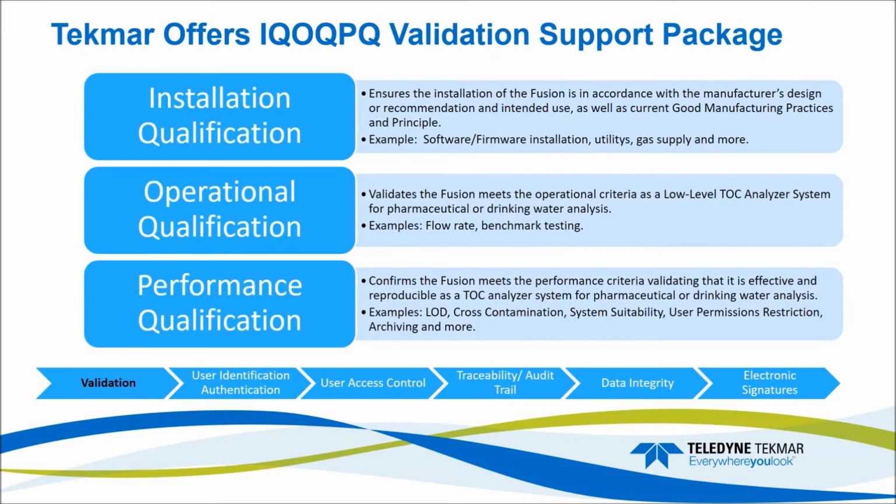All right, another thing we offer for validation, and this is offered by our service team, our field service engineers, is that we can come on site and do an IQ, OQ, PQ validation. We'll do your installation qualification, your operational qualification, your performance qualification, and go through that with you. You can also do it on your own and write up your own SOP for this, but if you want help, we do offer that as a tool to help you be compliant.